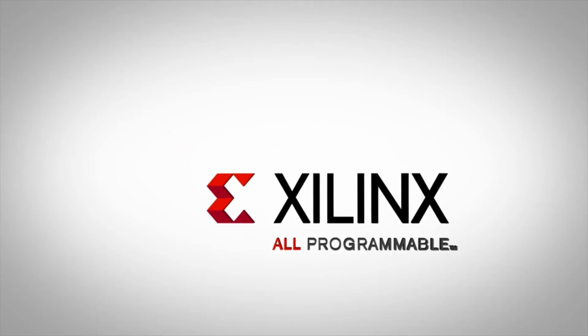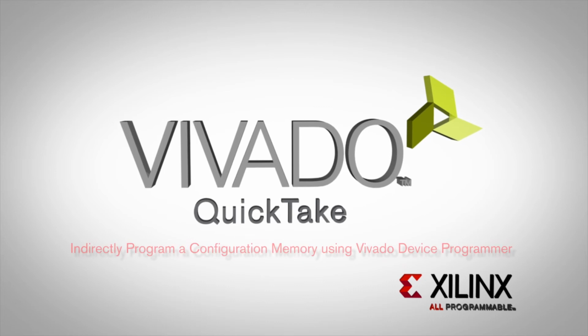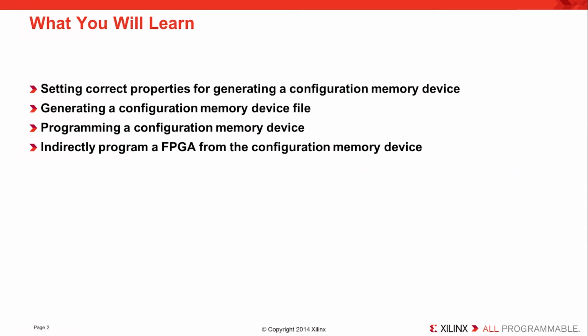Hello, and welcome to this Vivado Quick Take, where we'll be discussing how to use the Vivado Device Programmer to create and program a configuration memory device. Today you will learn how to set the correct bitstream properties for generating a configuration memory device. This is particularly important to ensure that the final bitstream is generated correctly.